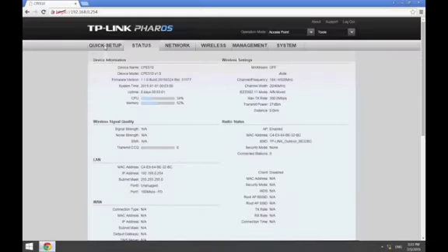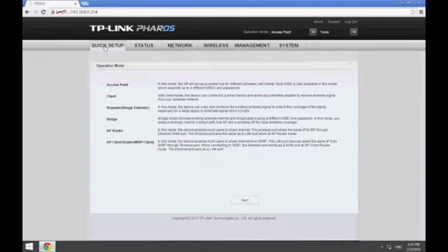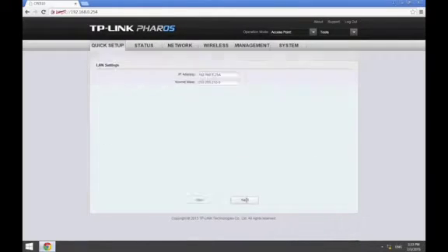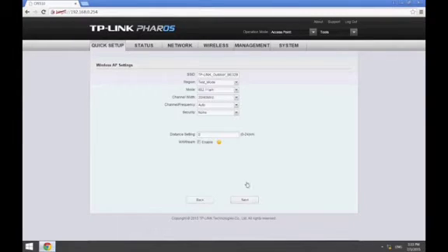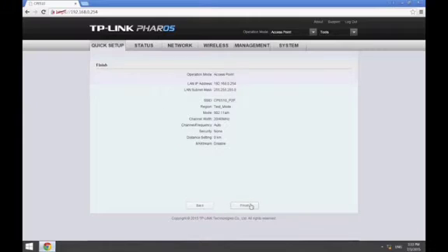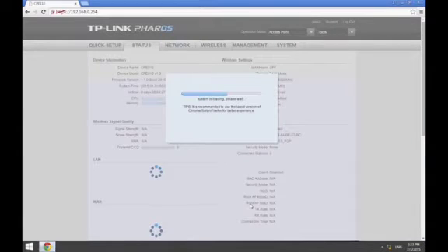Now click Quick Setup and choose AP mode. You can change the management IP address or continue using the default address. Here we change the SSID of this device to CPE510_p2p for easy recognition. The quick setup is now complete and you will be taken to the status page.